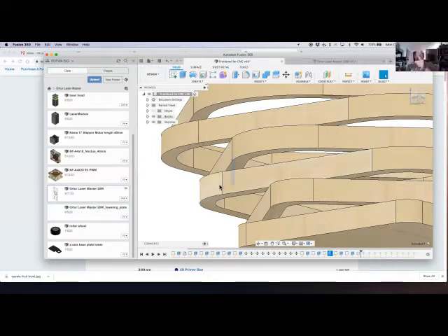Ah, so that's why you're saying the curve, because you reference the line of the straight segment, not the whole internal. Correct. No, the dimensioning's not that dynamic. In Fusion 360, that's going to fail. I mean, you do fillets and all those things by selecting those edges. Right. But in this case, they're like separate pieces still. Correct. Yeah. There might be another way to do it. Like maybe you could use a construction line around there and then put the hole on the construction line.